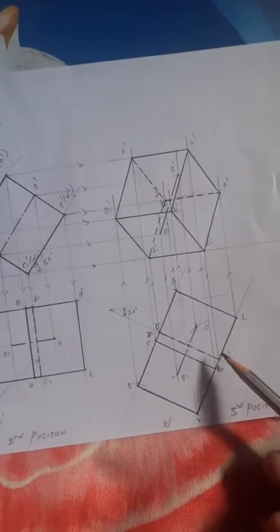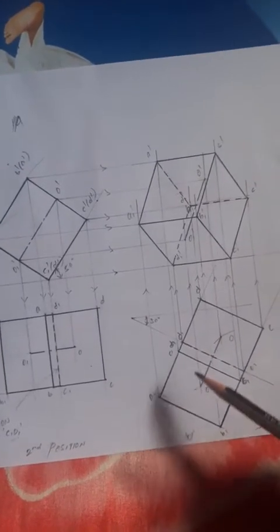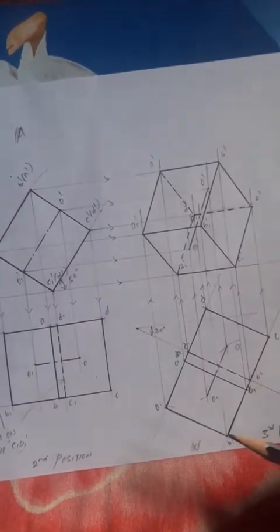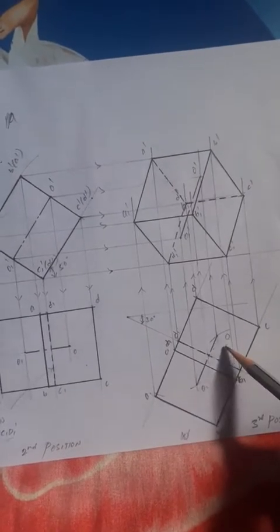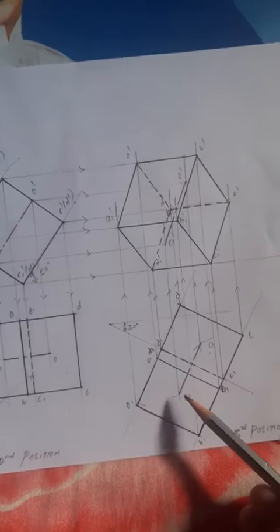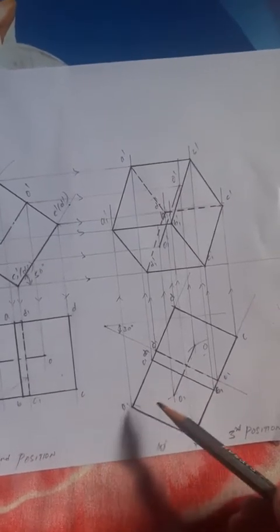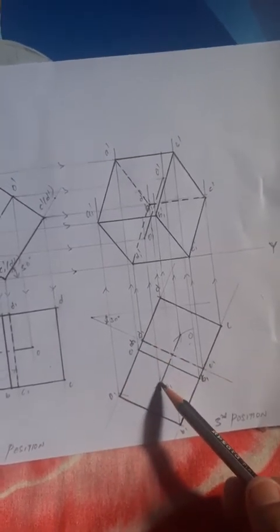Just rotate this second position top view solid and place it on the 30 degree line. How do you place it? Once you mark C1 D1, from the point C1 draw a 90 degree line. From D1 also draw a 90 degree line, right? On the 90 degree lines, with respect to this, measure the dimension through the compass, right? Then after that, how do you get O1? The best example here, I will go for the arc method. Instead of the arc method, as you know the base corners A1, B1, C1, D1, just join the diagonal corners A1, C1 and D1, B1. The intersection point will give O1.